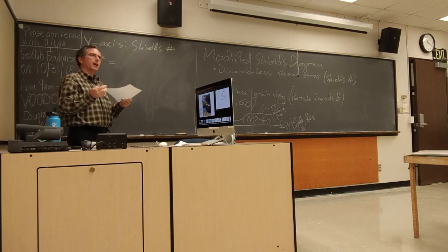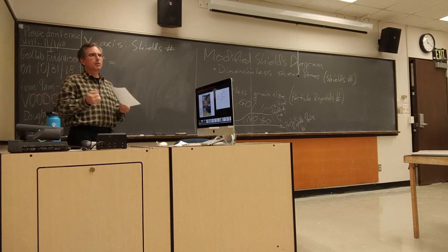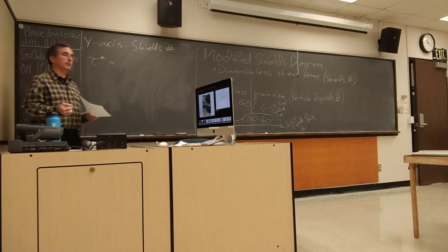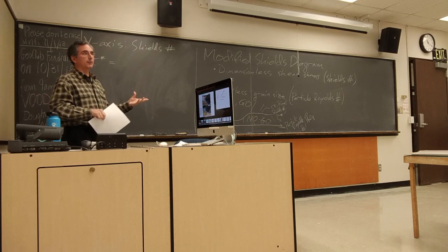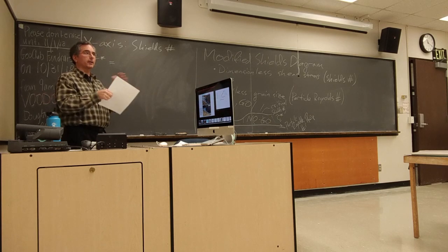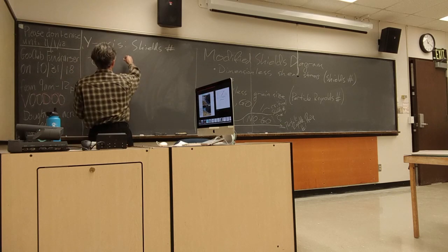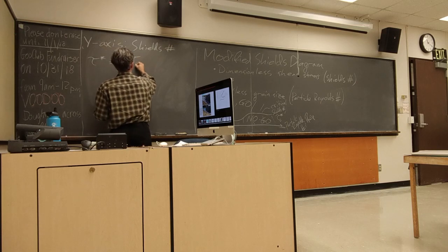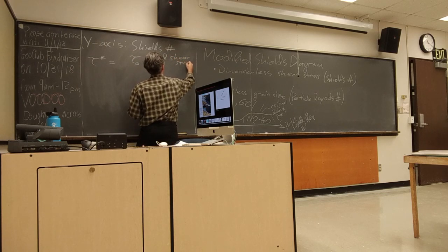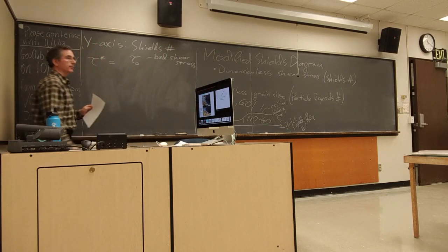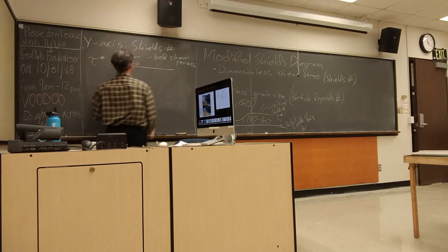So the idea being that, well, if I do an experiment with, say, ground up coal, or I do an experiment with a different fluid even, like oil or glycerin, or I do something on Mars, I can still calculate numbers that are then comparable to other numbers on that graph. So that bed shear stress is good old tau, and I've given it a 0 to indicate that we're talking at 0 height above the bed. So we're talking bed shear stress.